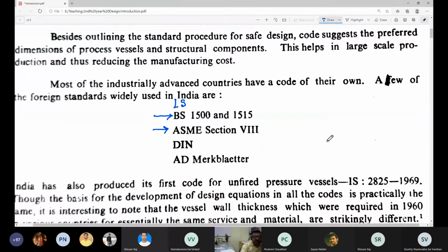So then you have to do the design differently. You do not calculate the thickness of the pipe. Rather, you accept some thickness of the pipe, and check whether it will rupture at that pressure or not. So there is a paradigm shift in the way the calculation is made. Then there are some very small things which one only gets to through experience.